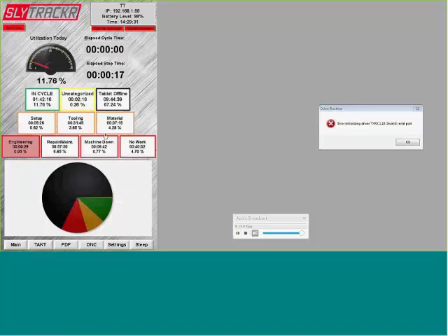There are seven different downtime categorizations. Another feature that we have integrated is the cycle start interlock, which you see popping up there. What we found after running this for a couple of months is the operators tend not to use the downtime reasons. So on the reports, we were getting either in cycle or not in cycle, and no reason why it wasn't in cycle. So we've made this cycle start interlock: the machine goes out of cycle until the preset stop time, which is 10 seconds right now.